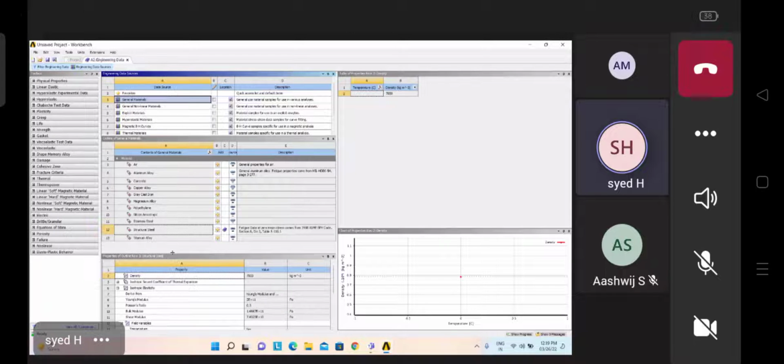There also we can check. Just now we checked structural steel, and when we change the values there, it will automatically come. How do we identify that the material is available in your library? See here, you can find a book symbol. This book symbol means it is used in a project. Right now it is currently available in your project. That's the reason it is showing like that.